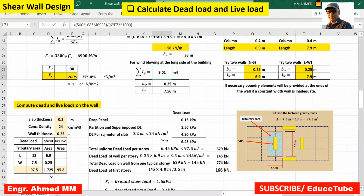Subtracting the shear wall area, we got the area for the live load. Now, here under the column there is a drop panel, so that load is here. Partition and superimposed dead load is given like this. Dead load per square meter of slab 4.8.